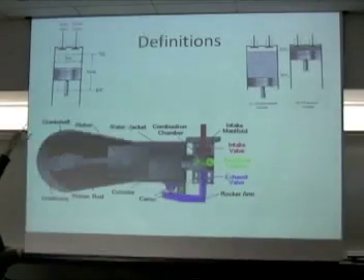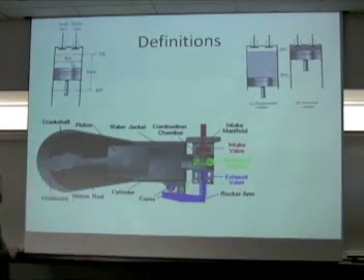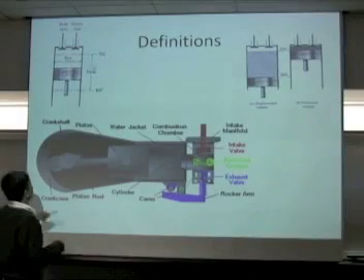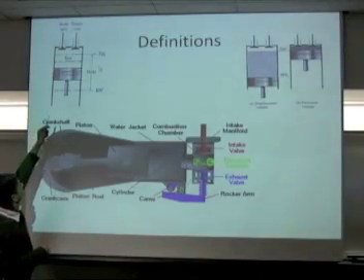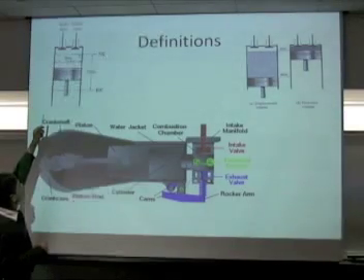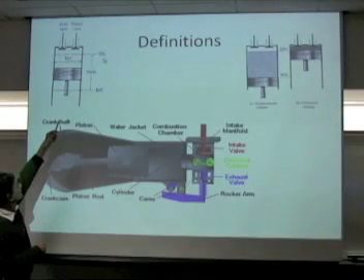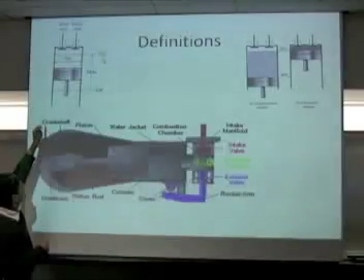If you look at that, the bore is the diameter of our cylinder, and what you see is the piston, which goes up and down, and we have an intake valve and an exhaust valve. When the piston goes all the way up to the top, which is called the top dead center, TDC, there will be the minimum volume inside the cylinder.